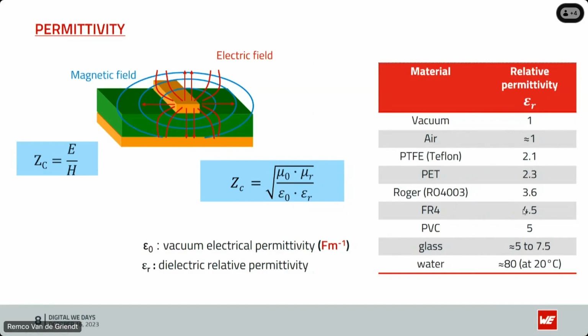So that's the thing you must take in consideration, because every change of your permittivity changes your characteristic impedance. A change of your characteristic impedance means that you have higher reflection losses or absorption losses or something like that. So that's what you must take in consideration. That's some sort of material on that way.